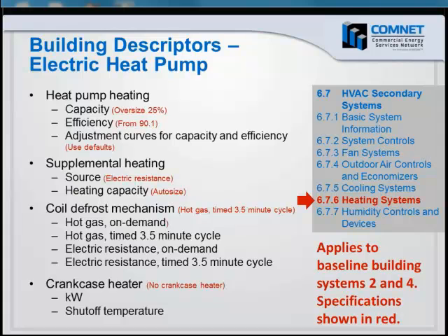What we need to do is to separate fans from that, which means that the heat from the fan should be taken out of the capacity, and also the power from the fan needs to be reduced, so that when you put in an efficiency number into the model, it should just be for the cooling and excluding the fans. And of course when you use EER or SEER or HSPF, those efficiency factors include the fans. So we have some equations for taking out the fan energy, which are included in the COMNET manual. That may have been what you were looking at.